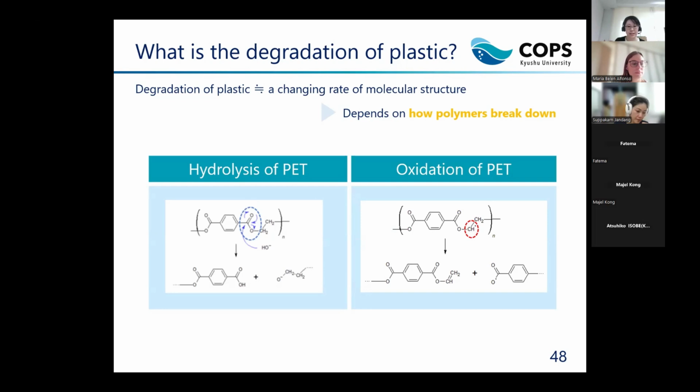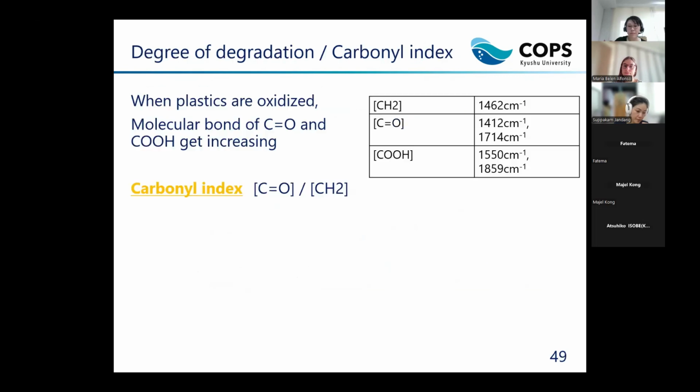In the case of polyethylene, it gets oxygen and forms a molecular bond like C and O. The carbonyl index is the ratio between the amount of the CH molecular bond and the CO molecular bond.